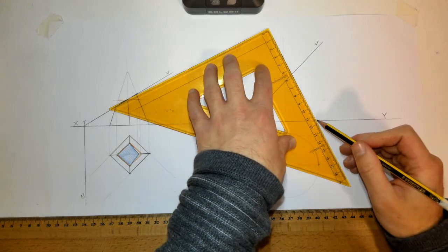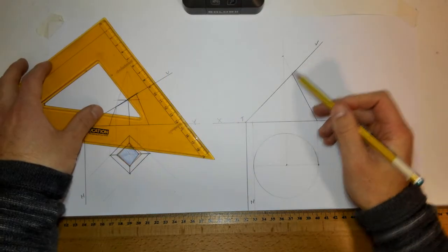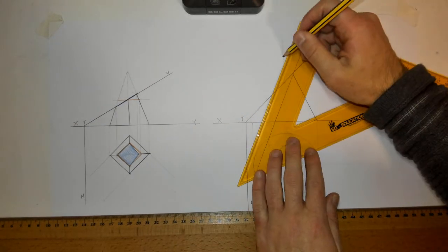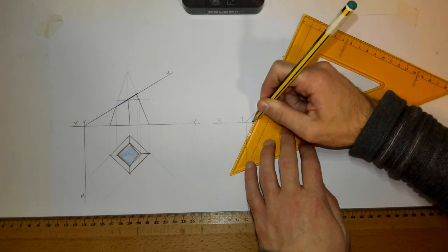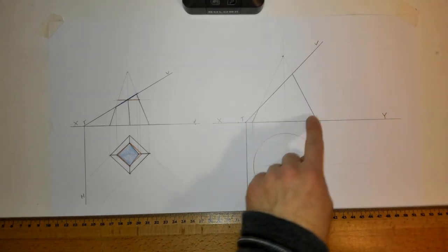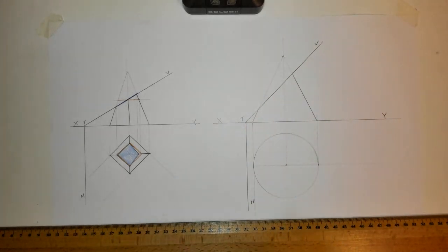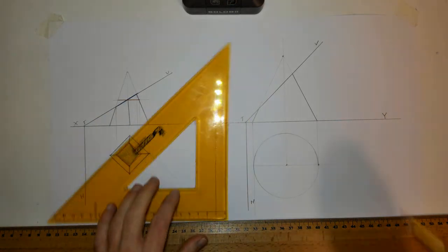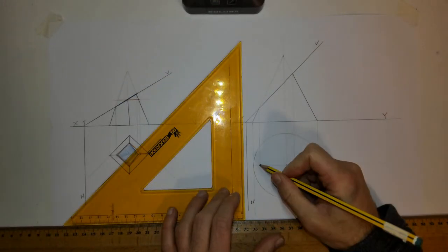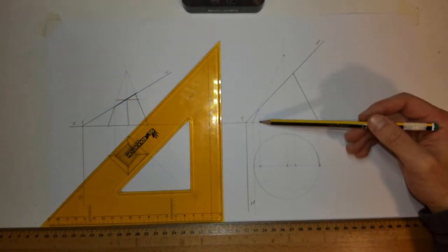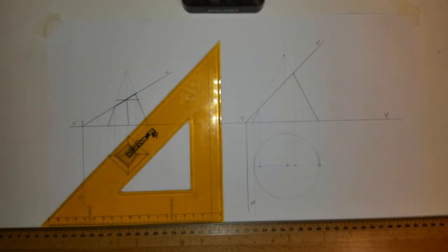Once again, because it's simply inclined, it's going to cut off exactly along that line there. So I connect those together, and all I've left from the cone is going to be this section here as a result. So my first point, I can take this line here, it's actually the extreme generator. I can take that down, giving me that point there, same on the opposite side, extreme generator down there. That gives me 2 points. You can see I took that line down, and that line down as well. They give me my 2 extreme points.